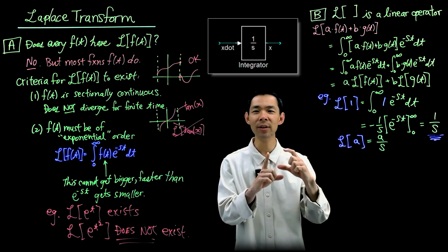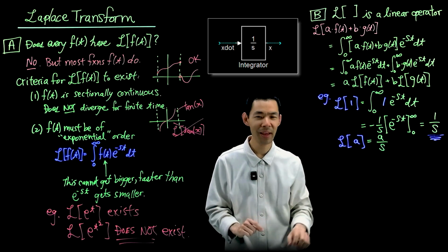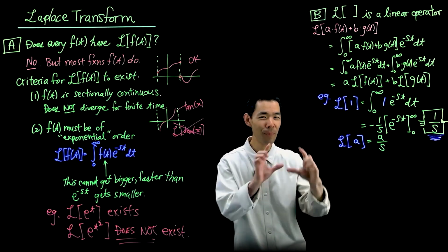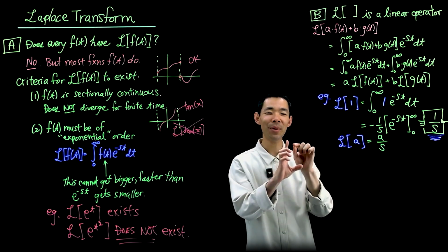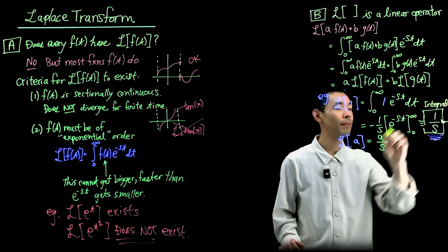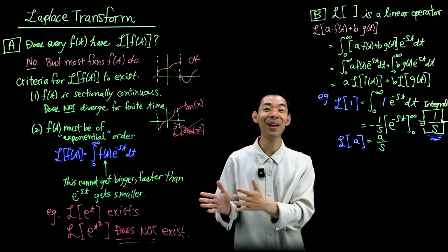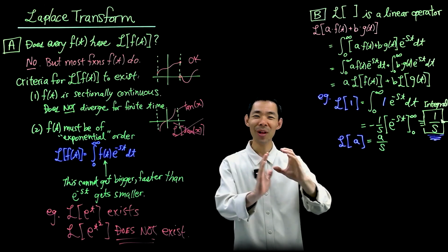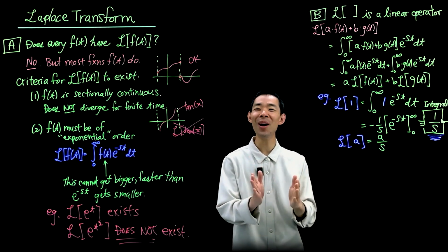Whenever you want to do an integral, there's a little box that says 1 over s on it. It kind of looks like this. There's a little box with lines coming into and out of that box, and inside that box it says 1 over s. It means an integral. And because everything on Simulink is performed in the Laplace domain, the block symbol for an integral is just 1 over s. And now you know why.